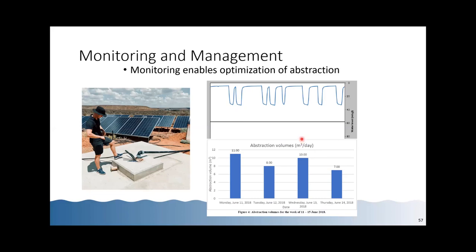And as often occurs, I couldn't even measure a water level at the borehole. So my first recommendation to them was, let's put a water level logger in. Let's see how your current abstraction is impacting on the aquifer. How are your water levels performing? And from 1 week of data, we got fairly good data where we see the rest periods, we see them switch on their borehole and the drawdown within the borehole, and we see the recovery within the borehole, followed by another period of abstraction and recovery.